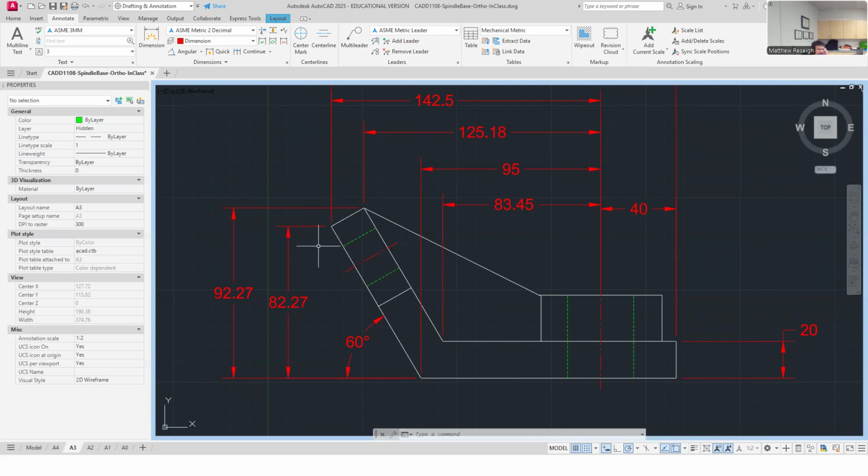And so let me just talk this. Some industries might say, while ASME likes this, some industries might be like, this looks busy and complicated, and I just want to know what this is, and we have these aligned dimensions. So I'm going to leave my ASME XY coordinate, but just know that in some industries, they may just prefer you to drop this dimension on here in an aligned fashion. They would be kind of breaking away from what ASME would tell them to do, but this would be where in industry somebody might prefer this dimension.